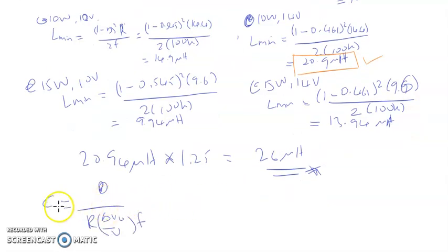For the capacitor value, C is equal to D divided by R times the filter range delta V naught, times F. In the actual case, we need to find the highest capacitor value, same as our inductor now, which can cater to all the conditions within our scenario: 10 or 14 volts incoming, 10 or 15 watts.